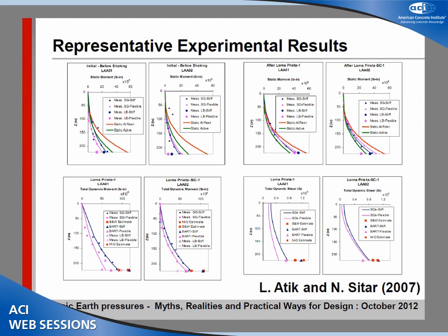Now, they went and measured what was the maximum moment at the base of these retaining structures, and the points are the data from their measurements. These outliers here are the results obtained if you use Mononobe-Okabe, which is for active conditions, which anyway shows that it is a conservative approach for the different earthquake motions that they considered in this experiment.